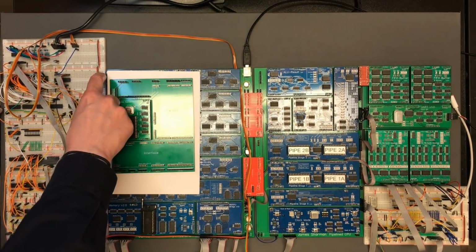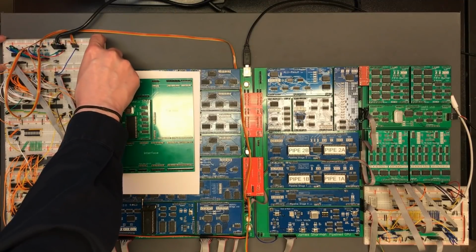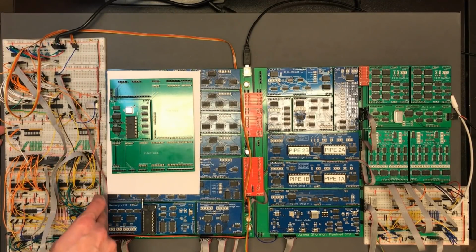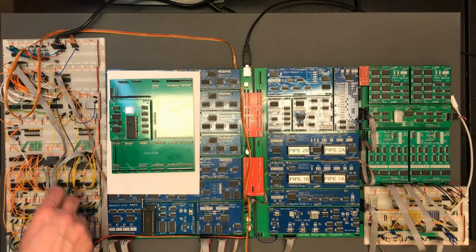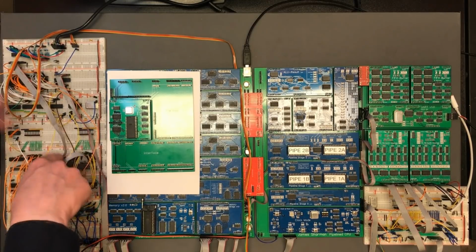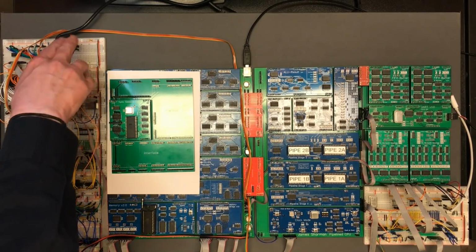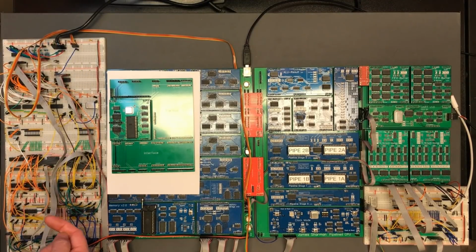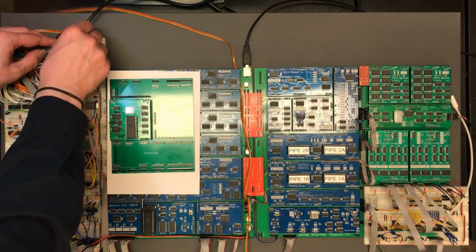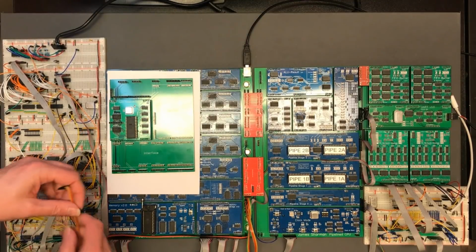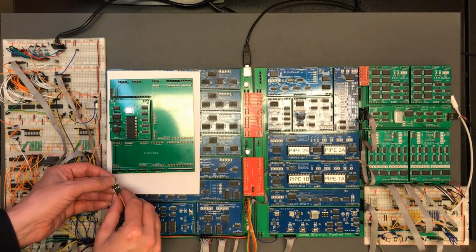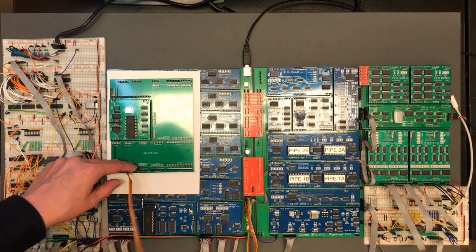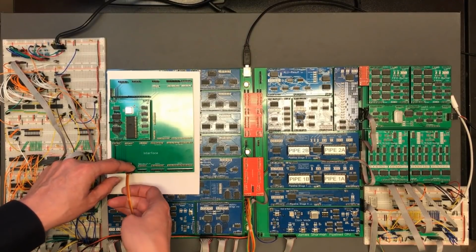Right, so these are the two boards that are coming out. We want to keep the output stage, keep all of this tile map and interfacing logic, and work out how to make the connections down that are going to keep it working and the connections up. So let's start with up. This is easy. That's the device control line. That can connect straight into the bottom there. Probably need a shorter wire for this, but that's going to do the job.